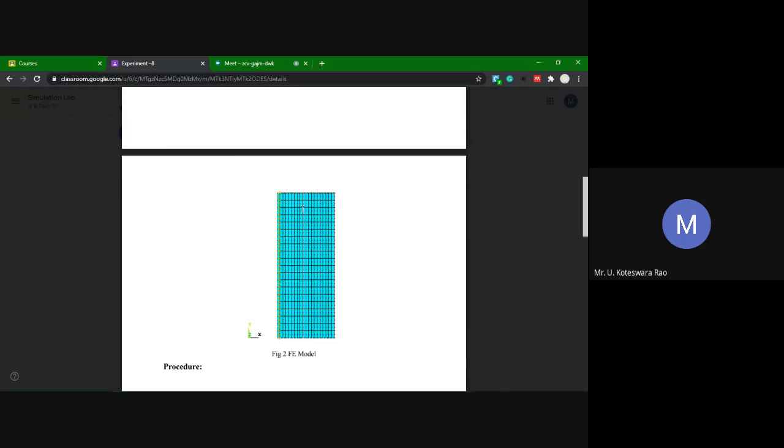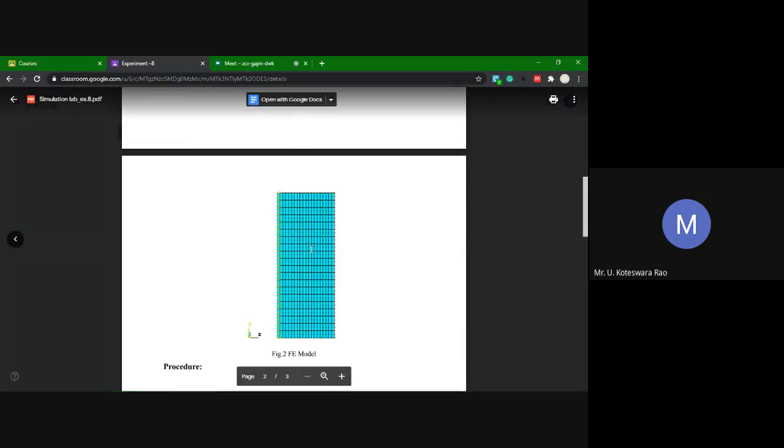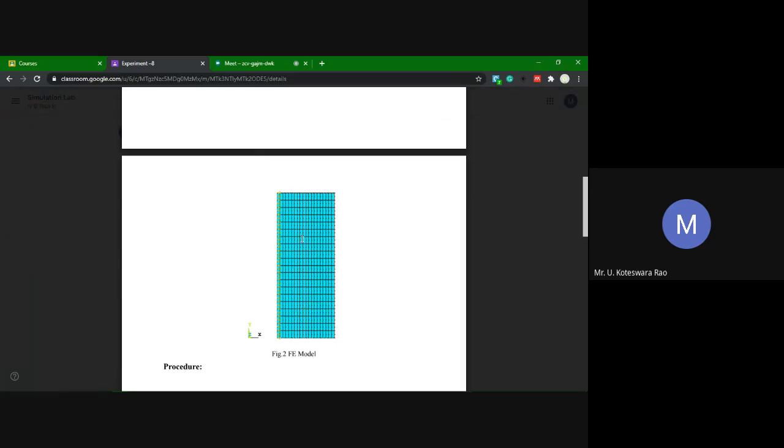Why is it 0? Like I already said, your temperature distribution is independent of length. If you take any length, it is not going to change. That means if I move in the y direction, the temperature remains constant. So what happens to your temperature gradient dT/dx? dT/dx will become 0. Since your heat flux q is nothing but minus k into dT/dx, and dT/dx is 0, your heat flux is also 0. So when heat flux is 0, I call it an insulation boundary condition.